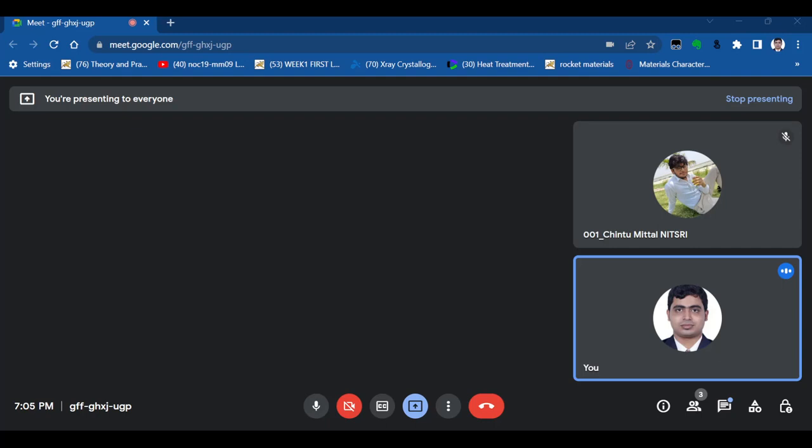Two identical engineering components are made from alloys X and Y. The K1C of X is greater than K1C of Y. If these components are subjected to the same stress, so the applied sigma is the same in both cases, during operation under mode 1 loading. Mode 1 means suppose this is our material, we have a crack here. Mode 1 loading means always the crack opening mode.